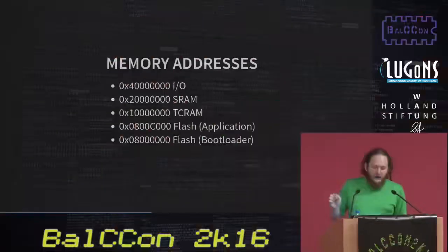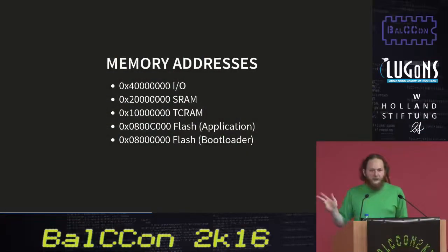If it begins with a 08, it's in flash. The bootloader is from 08004000 to 0800C000. At 0800C000, you have the actual application. This is the piece that we're interested in changing because all of the code at this address is what runs after the radio has turned on. The bootloader is only involved in firmware updates and in the initial startup process.